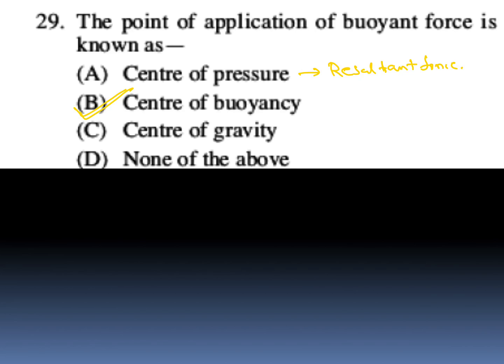And one more thing is important here. This buoyant force should always act through the centroid of the liquid displaced. It will not act through the center of gravity of the body. It will act through the centroid of the liquid displaced.